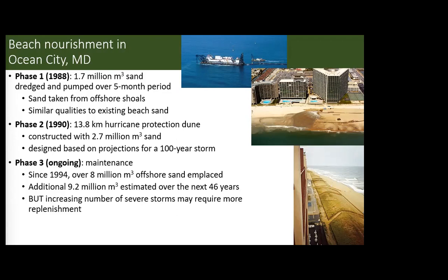When we calculate a 100-year storm, it's not a storm that happens every 100 years. Remember, we're not predicting, we're forecasting. So there's a probability of a very large storm happening within this 100-year time period. It's not like it's a clockwork machine that we're working with. We're looking at the worst case scenario and building to prevent that from happening.